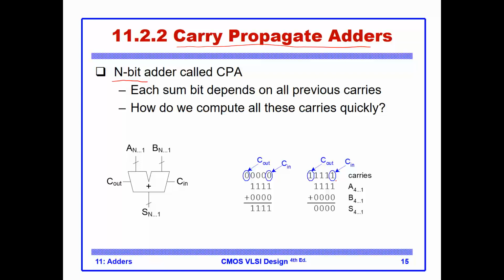In this case, you can see that we are adding this 4-bit number, which is A, to another 4-bit number, which is B. Notice here that we are doing this operation much like we have learned in digital logic. It is a multi-bit number added to a multi-bit number. Obviously, the answer will be multi-bit, and we will call this the sum, which has 4 bits, and we have a carry out.